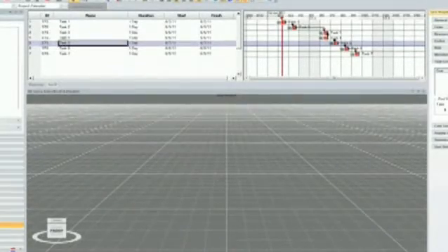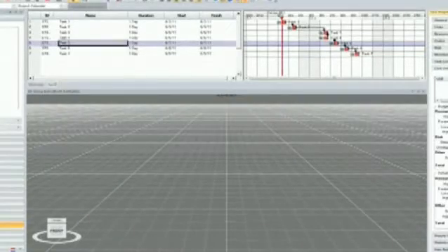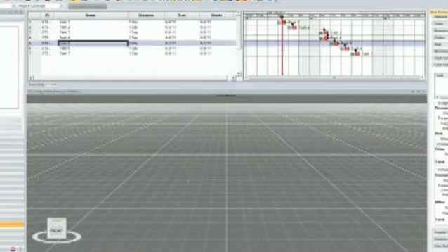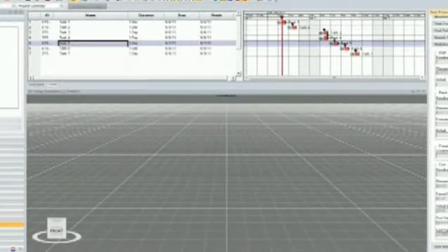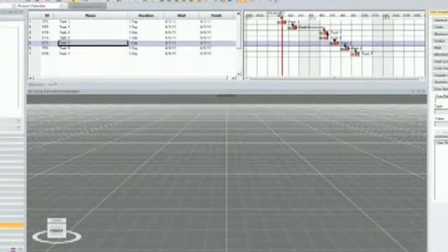Okay. We've also got task costs. So if you want to do a cost-loaded Primavera schedule, bring it into Synchro, all the costs come in, or you can directly input the costs into Synchro if you want to, but we do 5D from a cost perspective. And we've got cost totals, okay, resource, human, other totals. We've also got supply chain information on that task. We've got statistics on that task, so earned value of that task also. And then we have user fields, okay? So a lot of information in Synchro, a data-rich environment, so you can make great decisions about your project, okay?